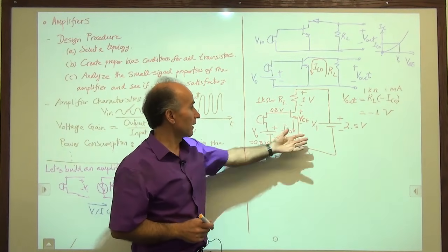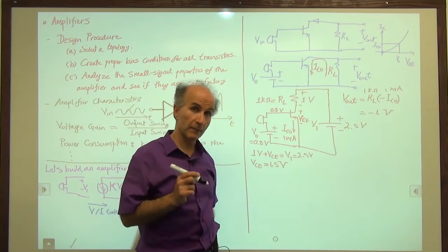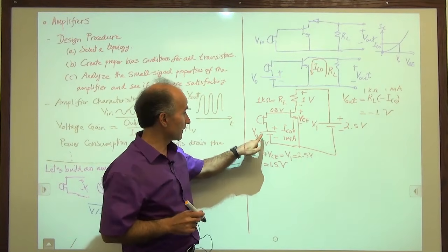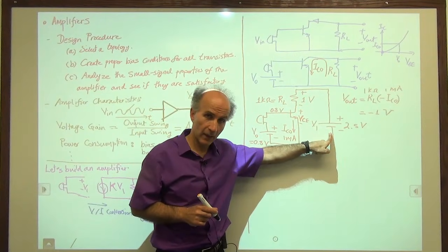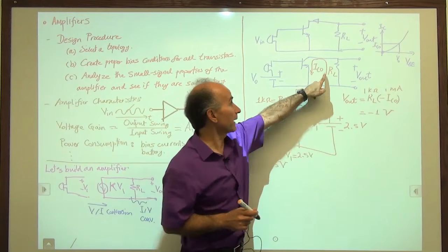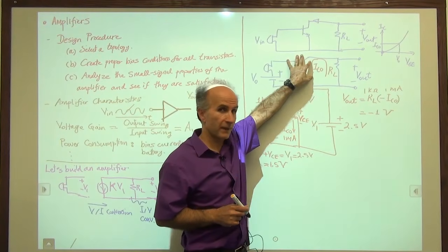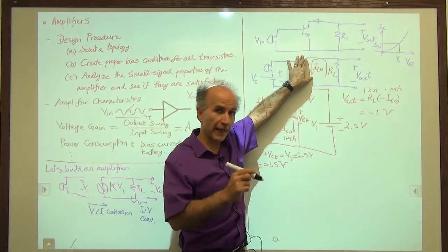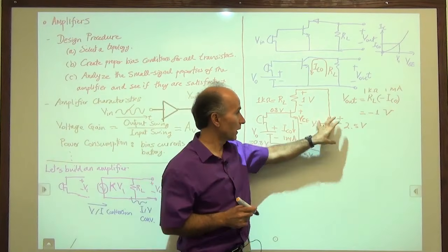Okay, so now we have an acceptable amplifier. This amplifier is biased properly by means of V0 and V1. Both of these are necessary. If we don't have V1, we are back here. This is not proper bias because the device does not operate in the forward active region. So we need V0 for biasing, V1 for biasing.